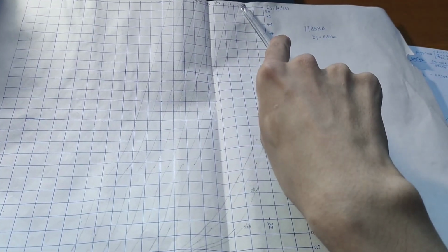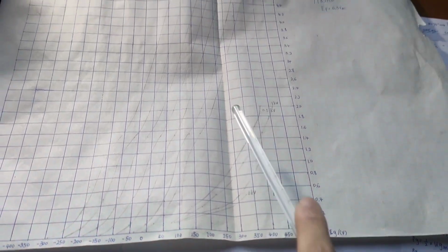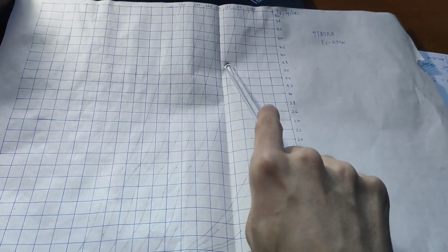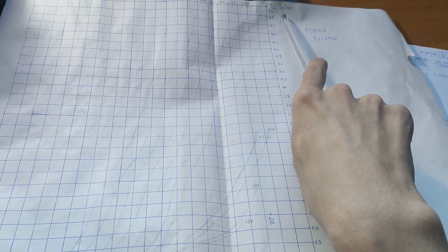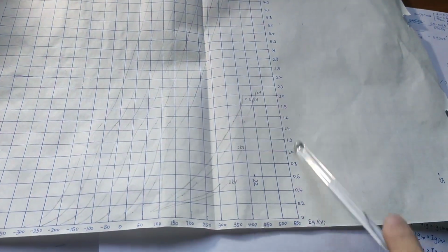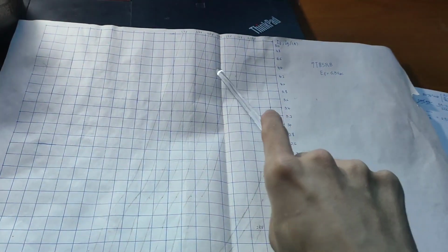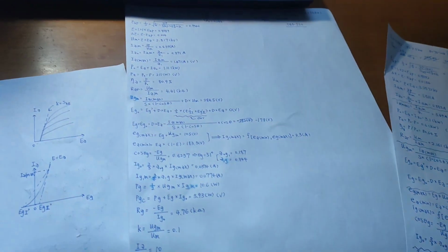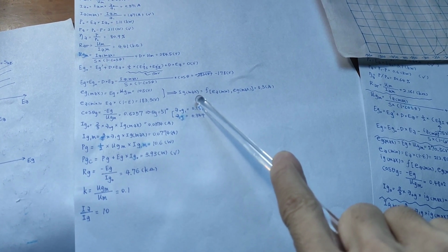And for example, if the anode voltage is 1 kilovolt and the grid voltage is 300 volt, we can see it is here. So we can just read out what our anode current and grid current will be. Here is the region for looking for the grid current, and this is for looking for the anode current. So just by doing that, we can get your grid maximum current.